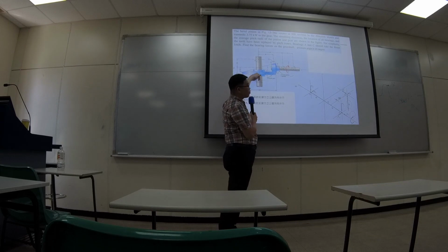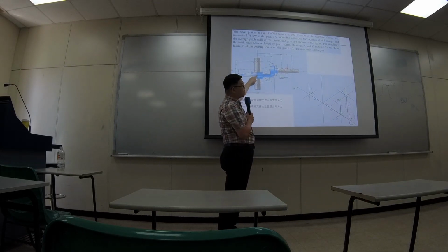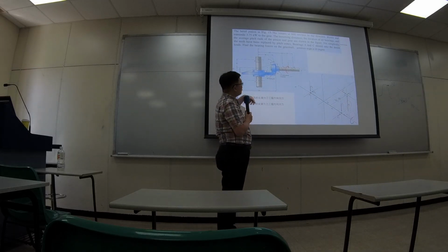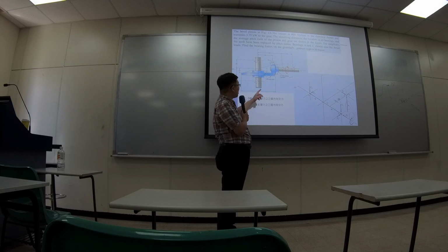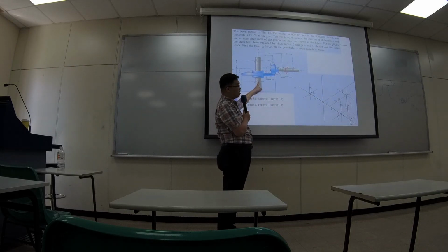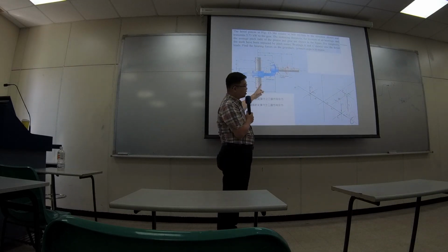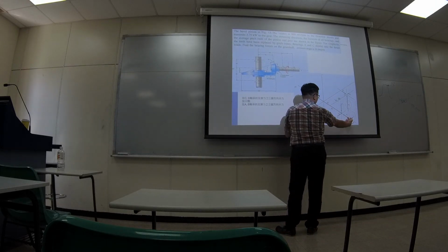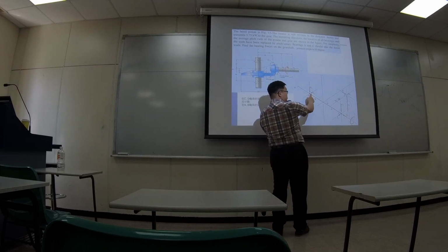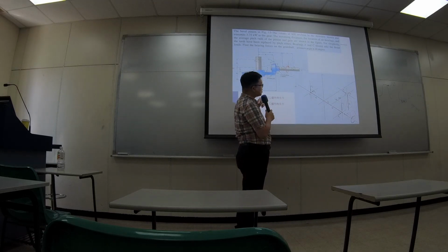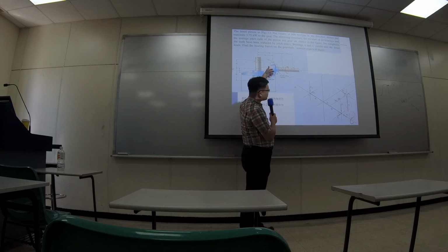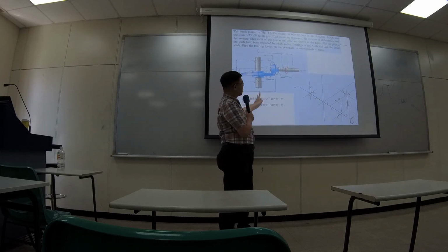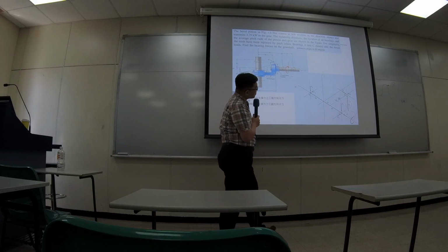If there's force pushing this bevel gear, you need something to carry the force. So that's a thrust, and that thrust is being carried by the bearing at C. So over here you see an FC along this direction, but this one doesn't have it. Whatever thrust is generated by the driving force from the pinion is going to be carried by C. So there's a reaction force here.